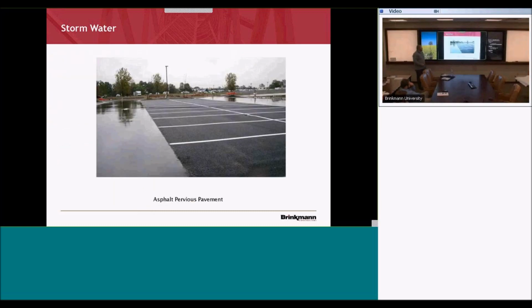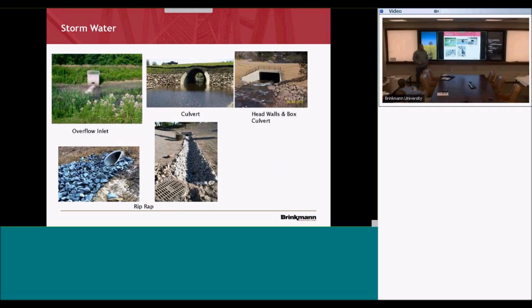Back up on that real quick. The other thing is make sure you got the fabric underneath it, otherwise the soil underneath washes away. Because you're going in an area of high flow, high concentration of flow there, and it's gonna want to peel the soil out. So you put some fabric or some geofabric under it, you don't have to go back.